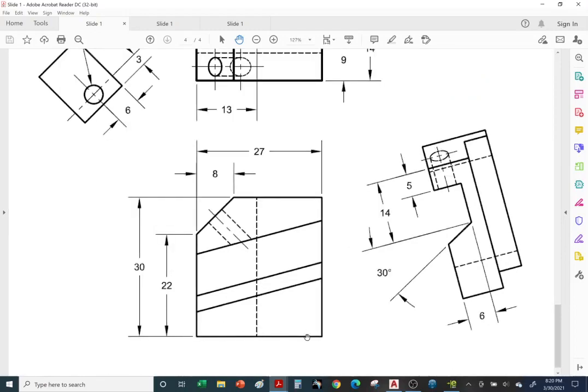So the datum on the bottom has a larger surface than the top. So this is our datum. So we'll dimension bottom to top, bottom to top. And then this surface back here has more surface area than the front or the left side here. So we'll dimension right to left, right to, oh, wait a minute, what's going on here? Well, this is a chamfer, so it makes more sense to dimension from this vertex of the chamfer to this vertex, okay?